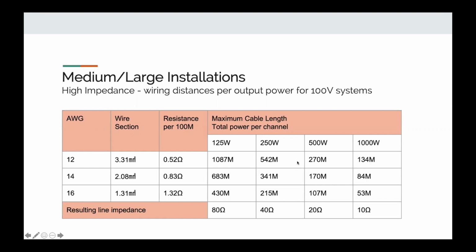you can choose the cable gauge according to the application, taking into account the amount of current you're driving down the cable and the distance that you expect the cable to go. Also, what you'll find with high voltage systems is that you will have amplifiers which will have multiple outputs, so you won't be expected to run significant distances.